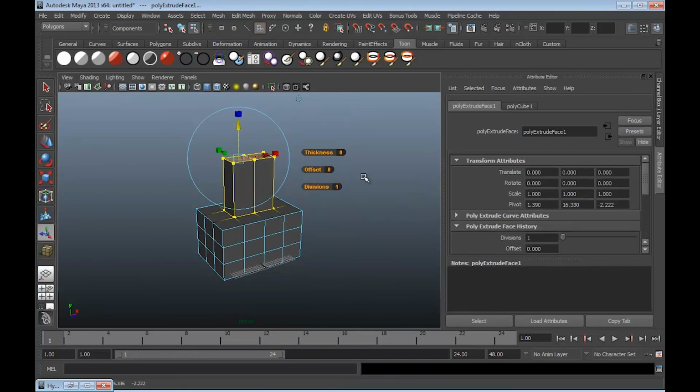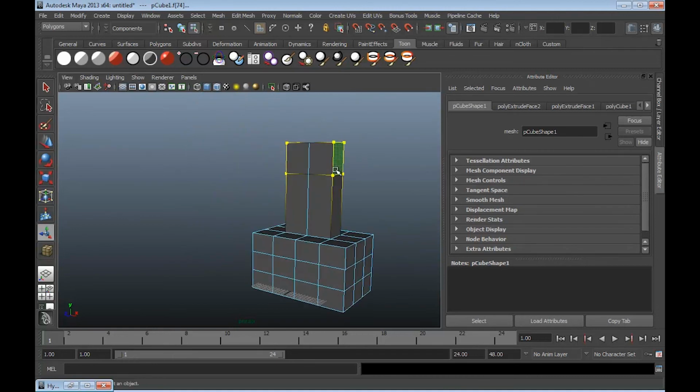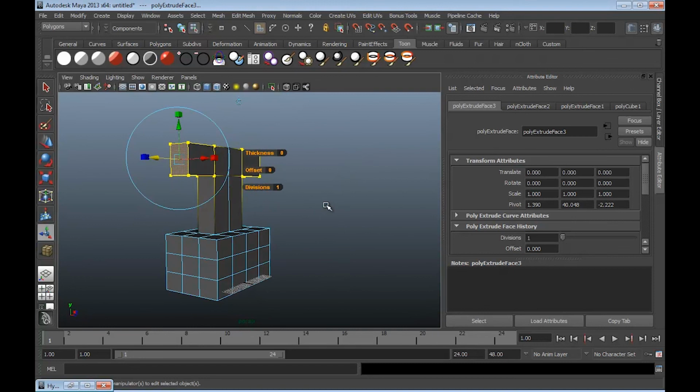And then I can hit G to repeat last command. That's right, G repeats the last command. I'm going to say that one more time for those of you who are taking notes. The G key on your keyboard repeats the last command. Very good. We can pull that up again, and grab these guys and hit G again. So cool, I'm doing some really, really basic modeling.